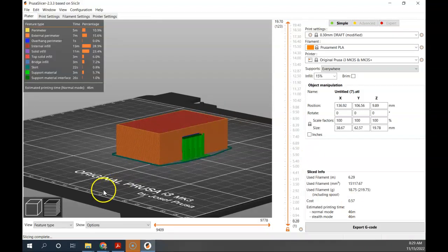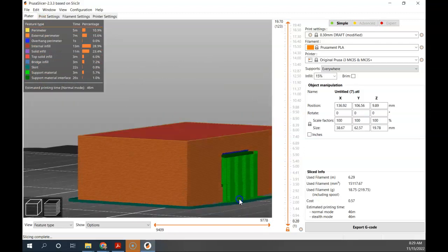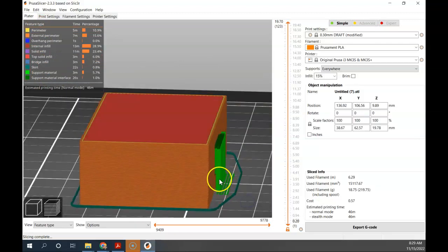And what you will see now is that there's some big changes here. And now we get to actually see the slices. We change a whole bunch of colors. The printer tells us and colorizes things to say what different materials are, what different parts are. You can see here that this support has been built here to make it easy to break away, and it tells us that it's green.